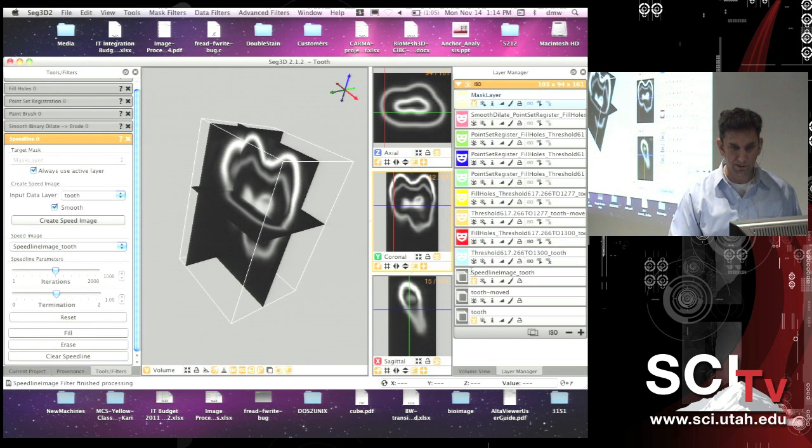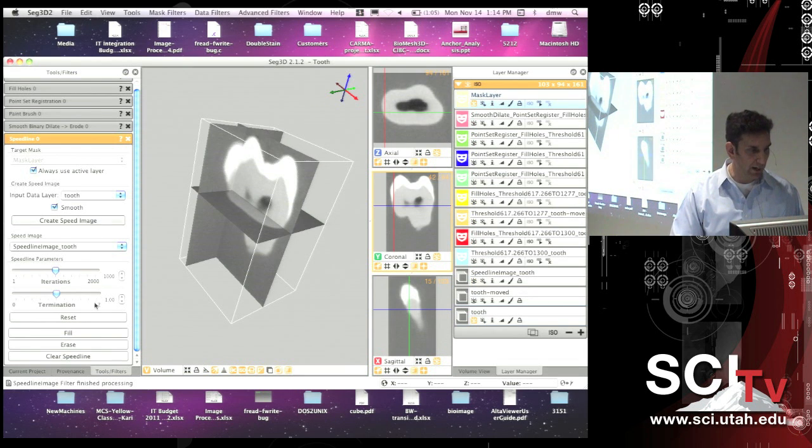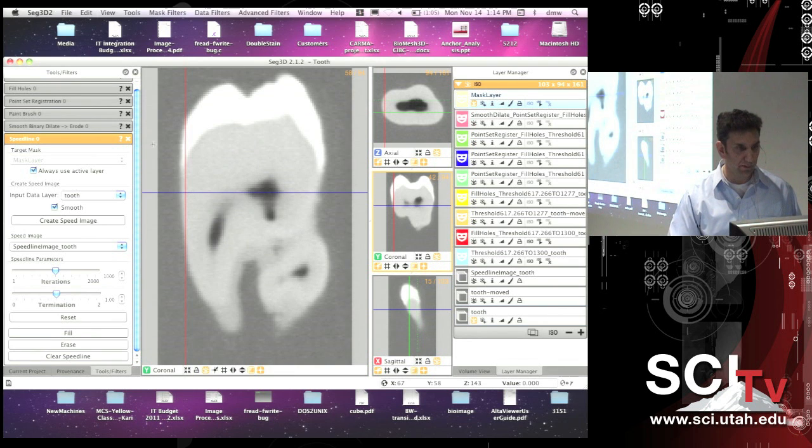It's basically the strength of the edges. You can turn it off. And then you go into your image here. So I'm going to switch over to the coronal view in my big window and start outlining stuff. So you left click, and it's going to follow the contour for you all the way around.